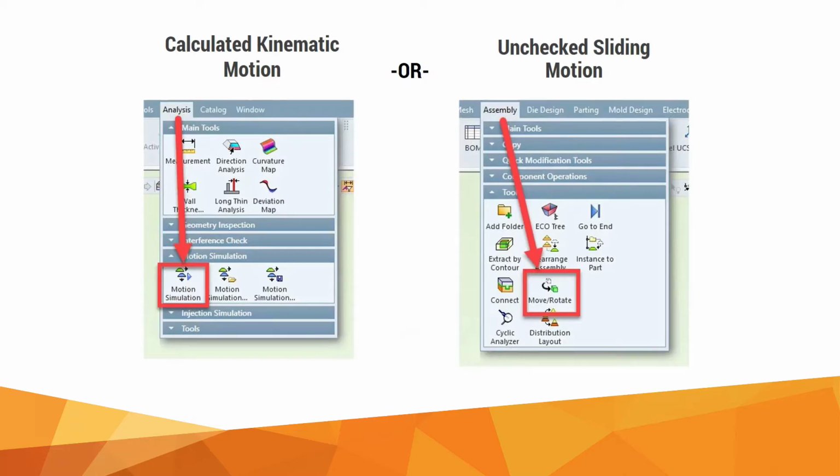The first and probably most important thing to know about motion analysis is that it uses a true kinematic engine. The motion of the bodies is calculated by the force you enter and the contact with other bodies. This requires the system to run a series of complex calculations over a span of time, but it means that the result is the actual mechanical motion of your mechanism.